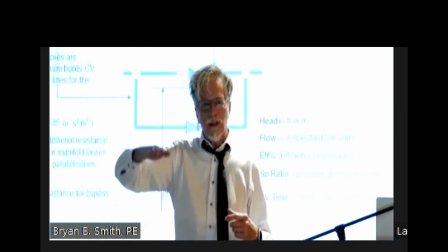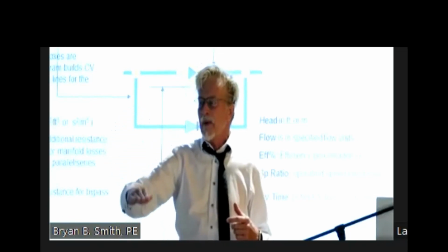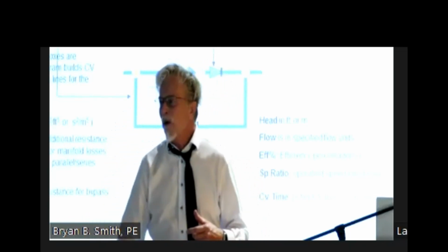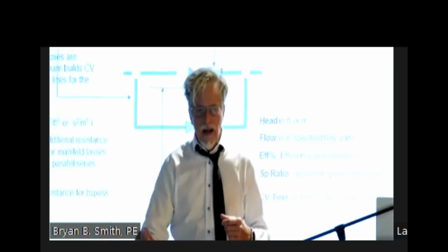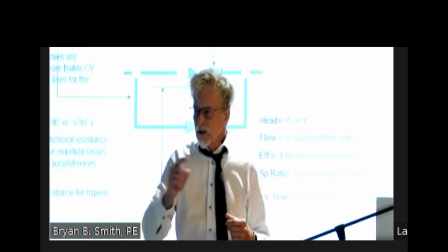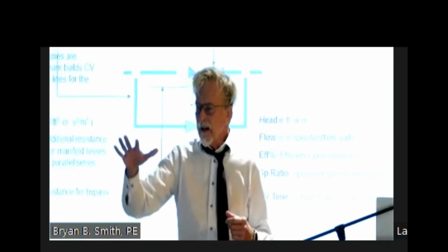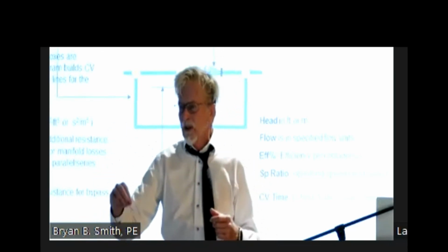Under normal conditions I'm at 52 psi, then 48 psi, and I'm not getting any water in that tank at all. So this is where we say, at midnight, turn off your pumps. The vessels, when you give energy, can work as pump cycle control. You'll see that vessel drop down to 30%.